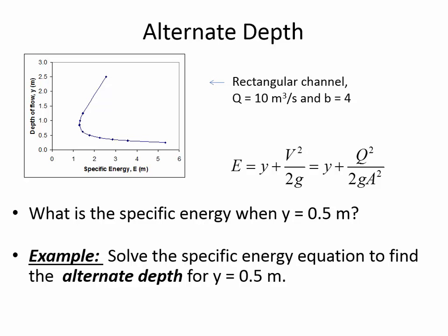No. What we'll do is we'll eliminate the depth that we've already got. There will be 3 possibilities. I think 1 will be negative, 2 will be positive. Yeah, okay. All right. So we can eliminate the negative root. The alternate depth is not some negative flow rate where the water is below the channel. And we're trying to find what's the alternate to 0.5.